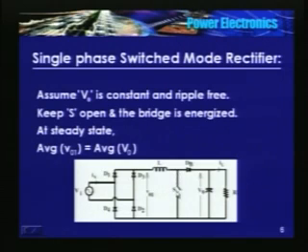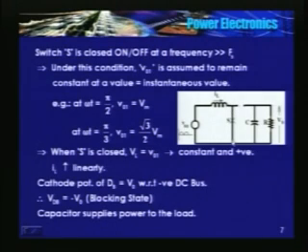And at the input there is a short circuit. So here is the equivalent circuit: a rectified sine wave, an inductor, the switch is closed so there is a short circuit here, there is an open circuit here because the diode is reverse biased, the voltage appearing across the diode is VO, and a load. I told you that switch S is closed at a frequency much higher than the supply. So what we can assume is that VO1 remains constant at a value equal to its instantaneous value.